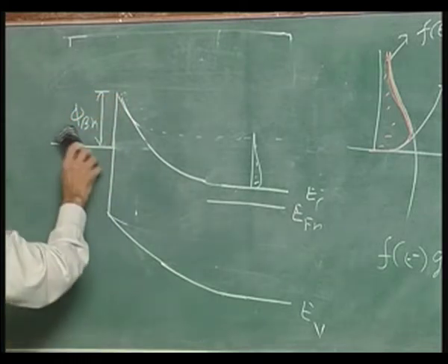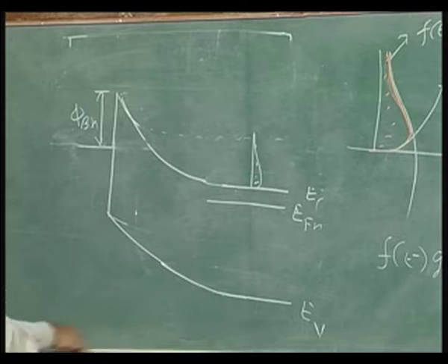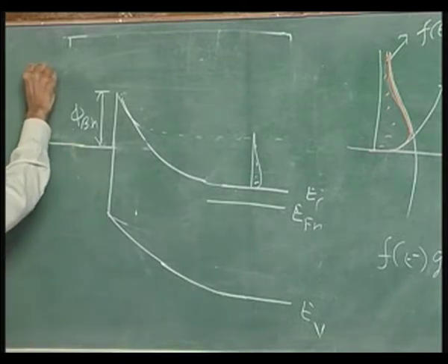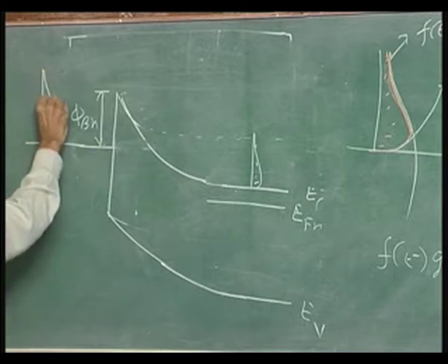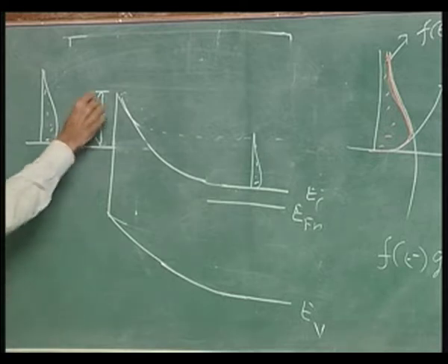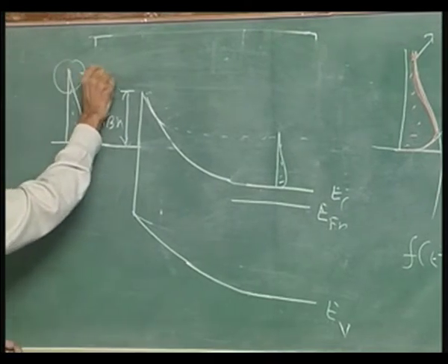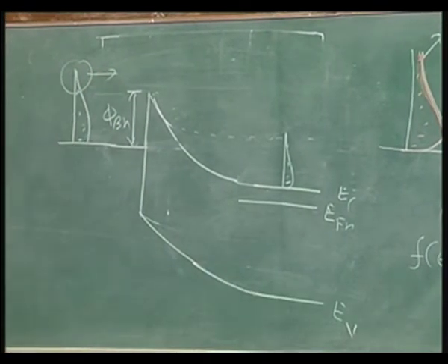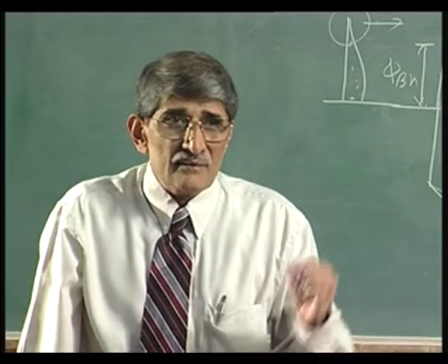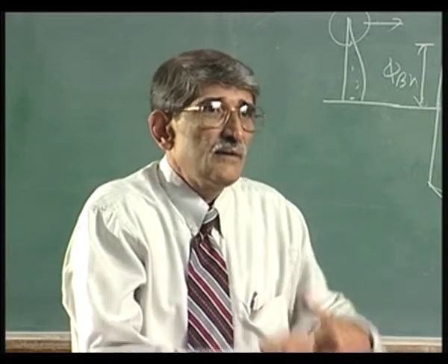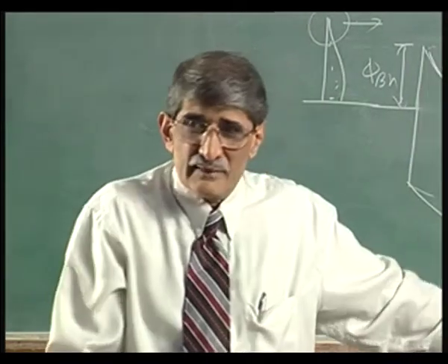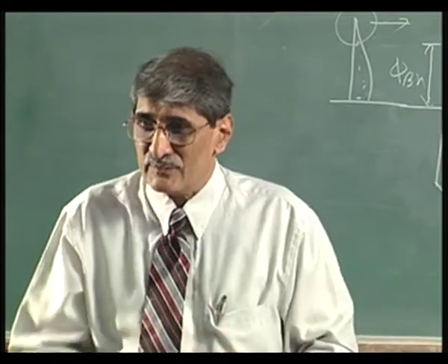Okay. So, as far as the electron distribution is concerned, here what has happened? We have drawn it earlier like that, thermal equilibrium situation. Whatever electrons are there, they can cross the barrier still, okay, that barrier has not changed. Whatever was giving rise to current, electron transfer from left hand side metal to the semiconductor, remains the same thing, that we called I naught.